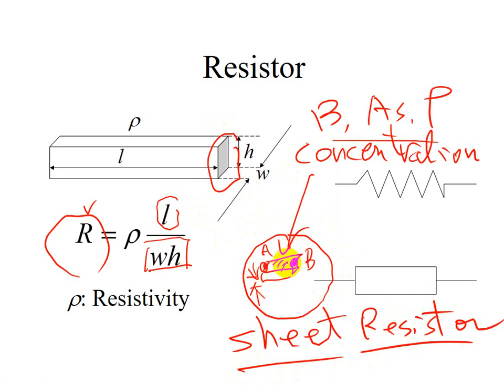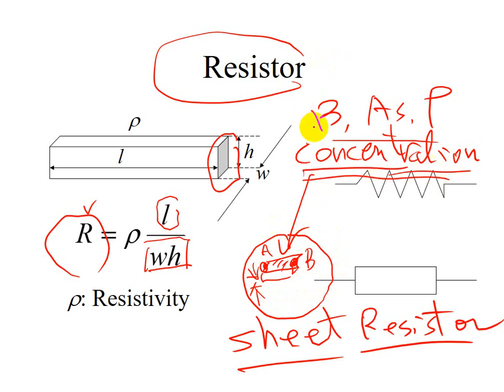So now you know how to simulate a physical resistor in a circuit design onto a silicon wafer by defining an area with a certain depth of dopant. By controlling the concentration of the dopant, you're controlling the concentration of the charge carrier. The more the charge carrier, the higher the conductivity, the lower the resistance. This is the first device we call resistors.